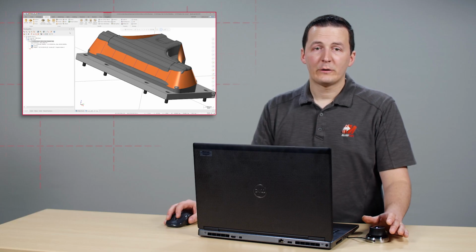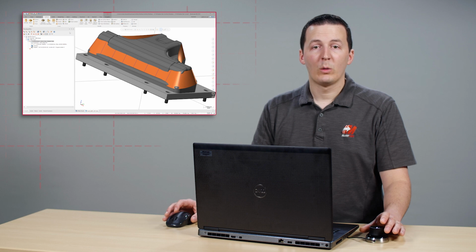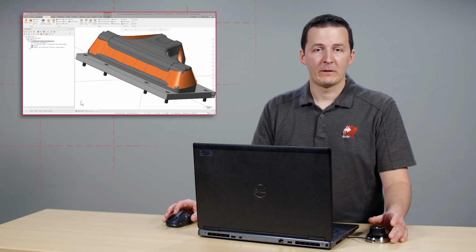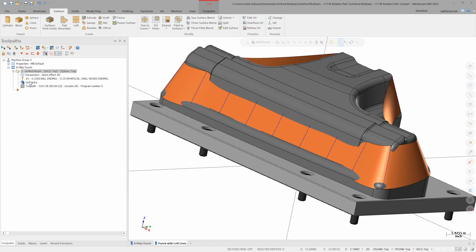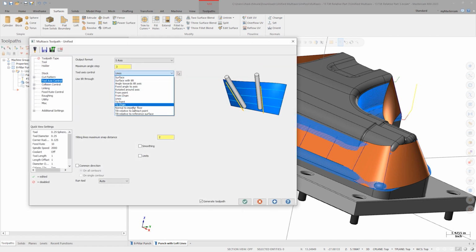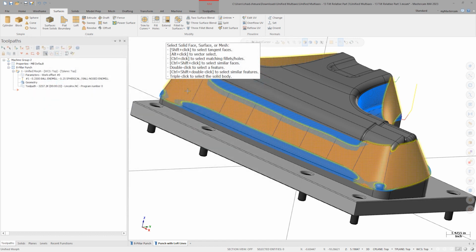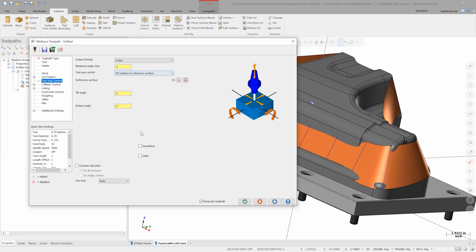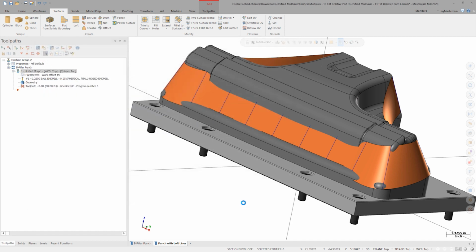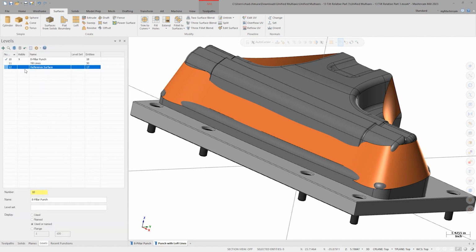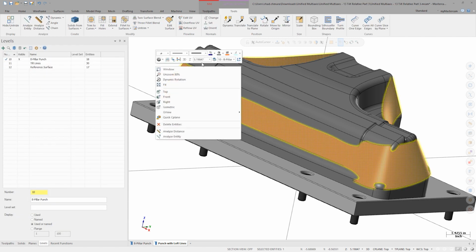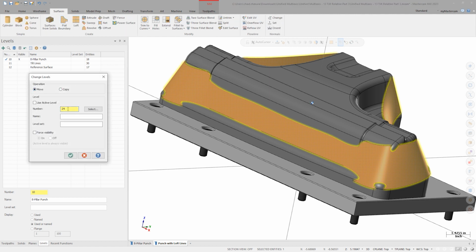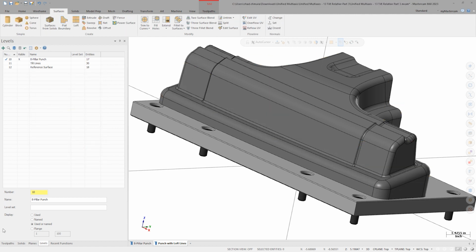As you can see, this surface is far from precise, but it will work wonders as a tool axis control reference surface. Again, be sure to activate tool axis control smoothing when using tilt relative to reference surface. In this instance, this powerful smoothing tool removes 90% of the rotary axis reversals created by this tool axis control strategy. Generate and backplot the toolpath.